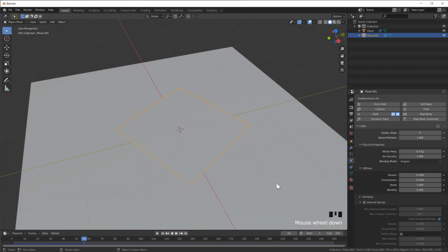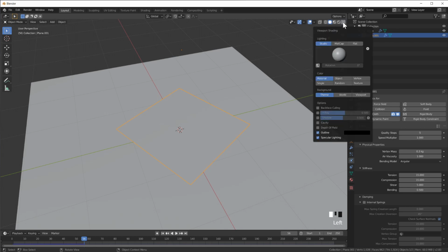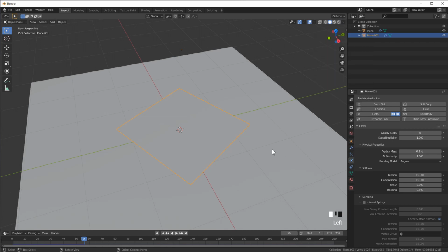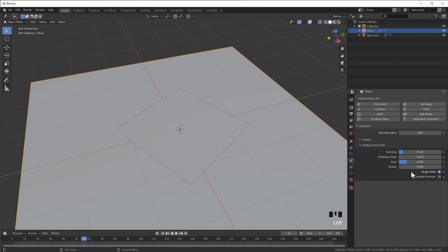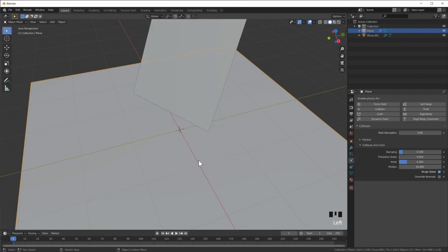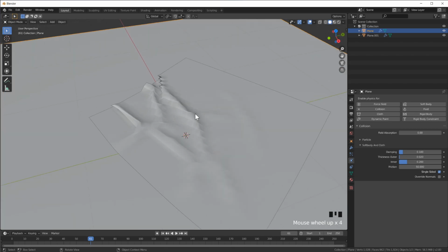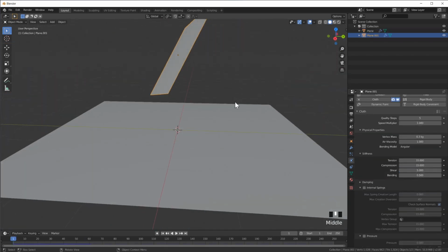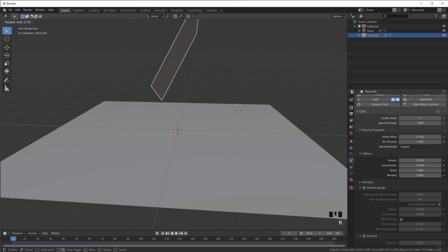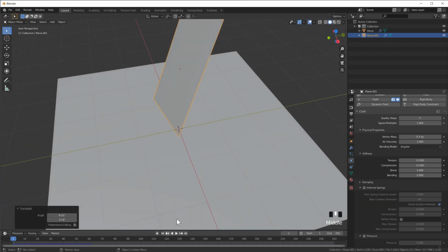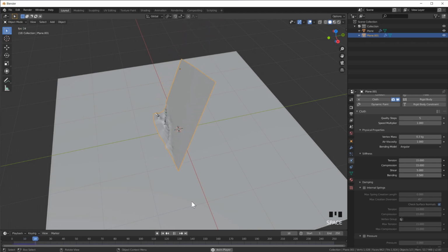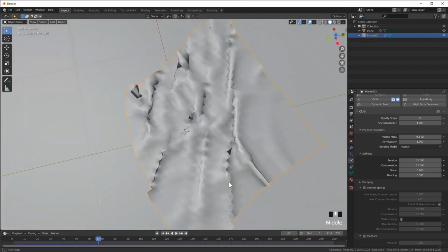Now this looks very, very plain. Nothing special going on here. So we have to play with some of the settings. First of all, we can go to the collision object, to the ground plane, and turn up friction so that when the cloth falls down, it actually sticks to the ground and then we get wrinkles. We can actually rotate this even more maybe. Go shift left arrow, space bar. Now we have a cloth simulation.